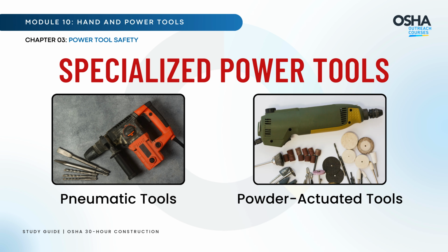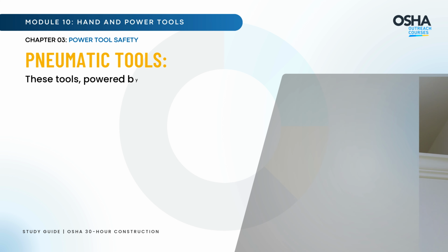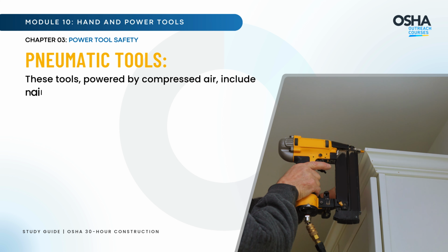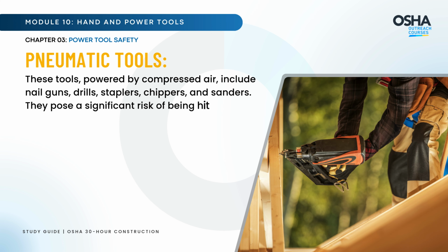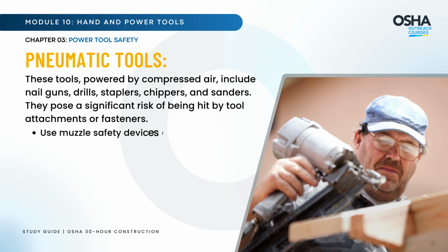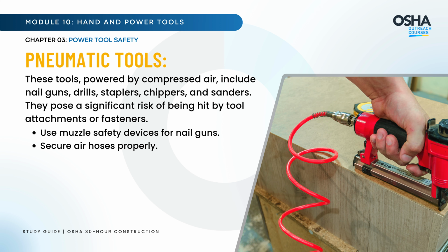Now here are specialized power tools. Pneumatic tools. These tools, powered by compressed air, include nail guns, drills, staplers, chippers, and sanders. They pose a significant risk of being hit by tool attachments or fasteners. Use muzzle safety devices for nail guns. Secure air hoses properly.